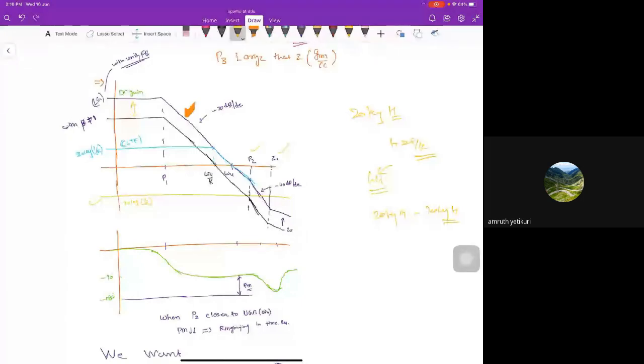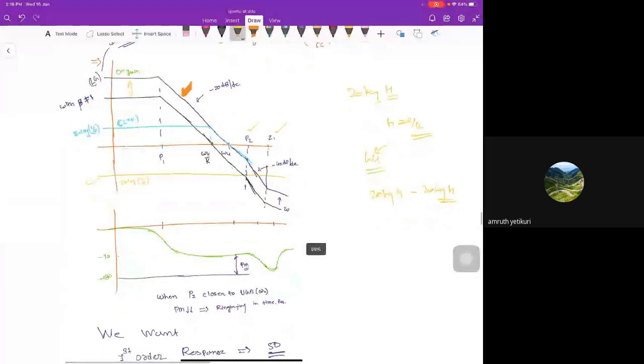So let's see this effect here. In a closed loop transfer function, we have already seen that below the UGB of the loop gain, my gain will only depend on the feedback factor, that's the 20 log 1 by k, and above the UGB my gain will follow the G curve. That's why I plotted the blue curve like this.